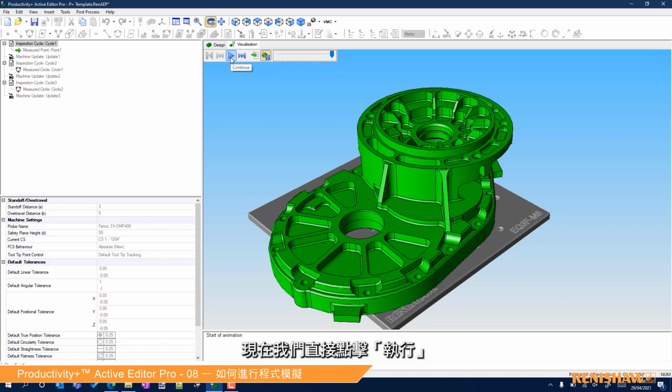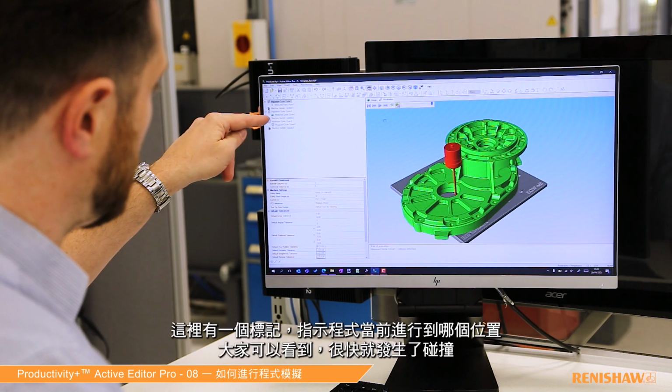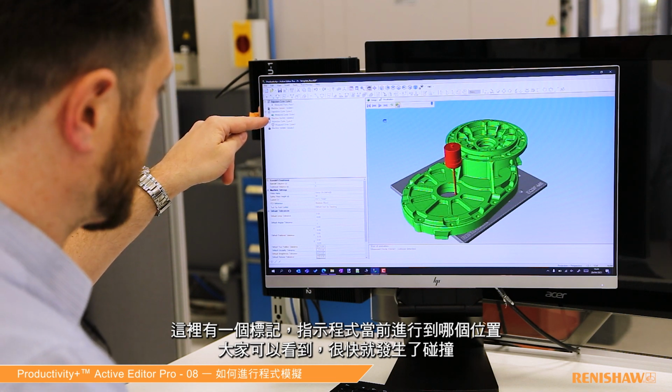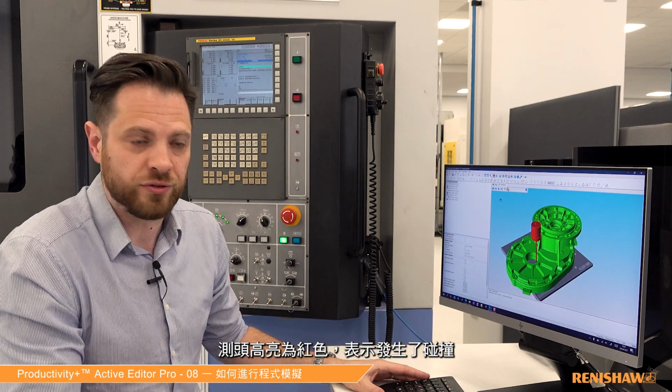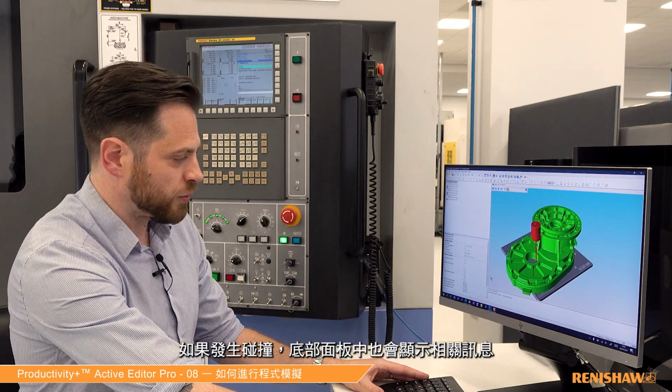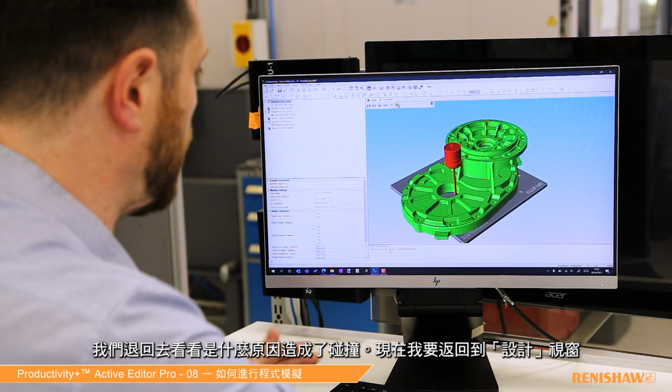So for now, let's hit play and see what we've got. So we're simulating the probe. We can see the marker there as to where we are in the program. And instantly now what we can see is we've had a crash. The probe's been highlighted red to illustrate that. It will also say in the bottom panel here if we've had any collisions. Okay, so let's go back and have a look as to what's caused that collision.